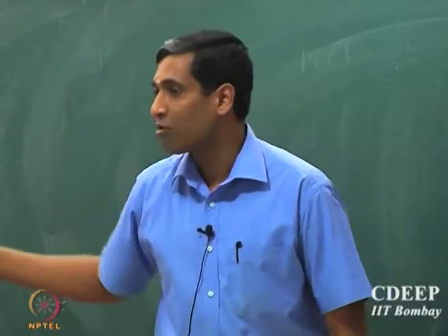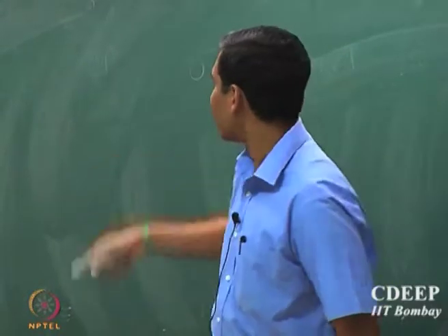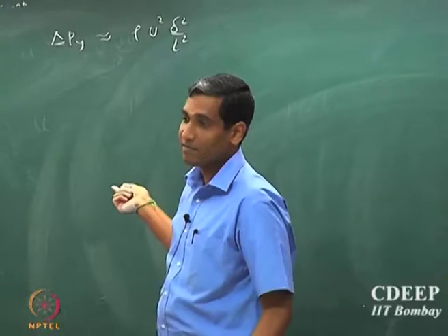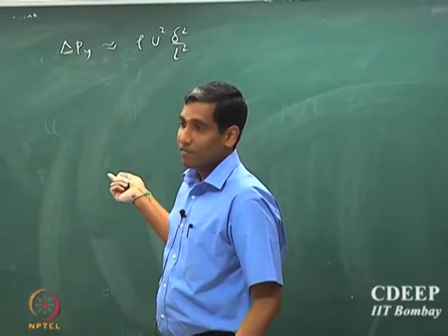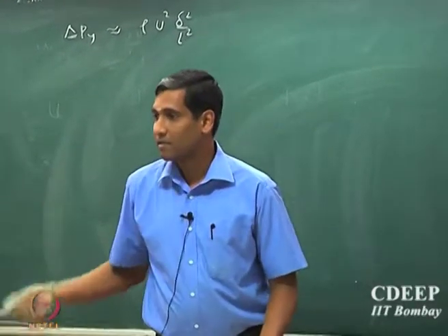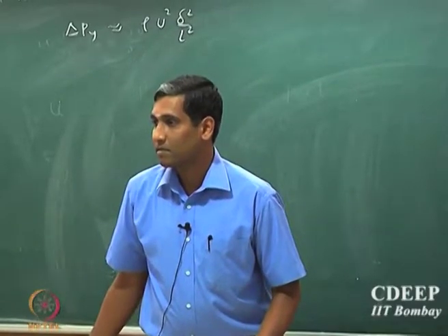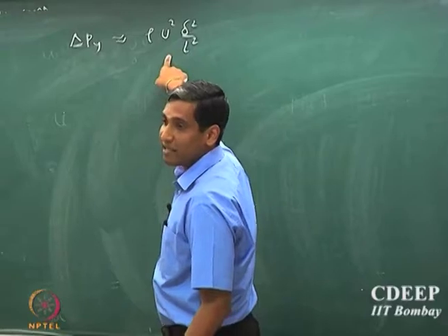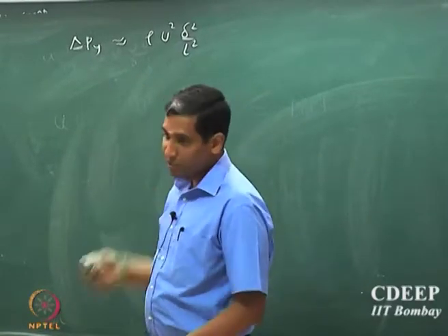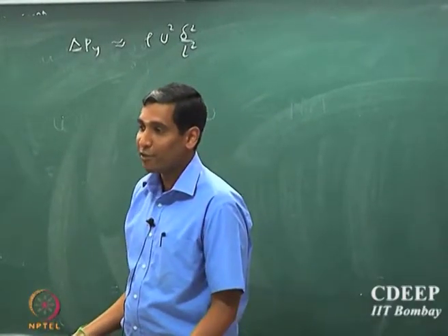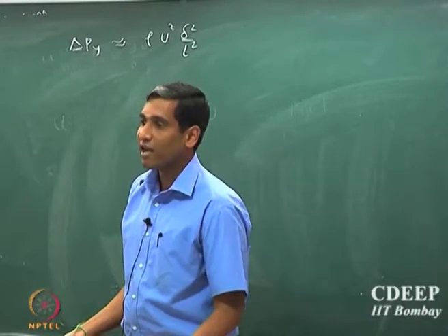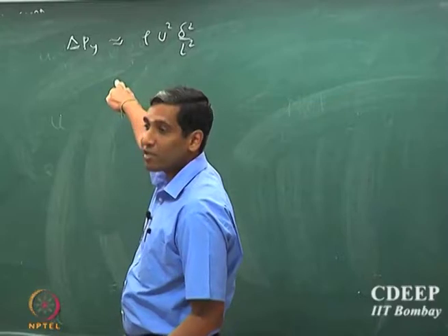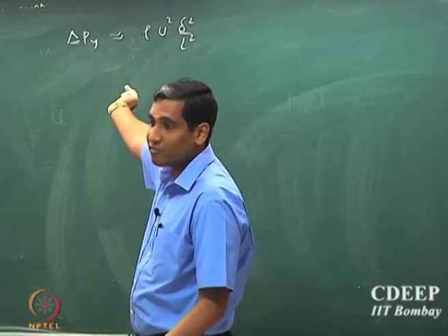Now you can't cancel out any terms. All you can say from that is only that the pressure is approximately constant. If you assume that the delta Py which comes out from the scaling is approximately constant, then it reduces to dP by dy being 0, because all the other terms, although comparable, are very small, and therefore dP by dy has to be 0.